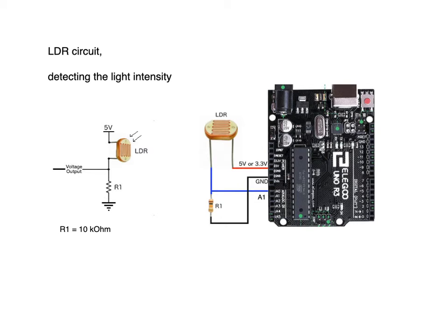We connect the pull-down resistor between the LDR sensor's other pin and the ground. The sensor data is taken from the same pin where the resistor connects, and it's connected to the Arduino's analog pin. Any of the analog pins from A0 to A5 should work, but make sure that the pin that you select is the same pin that you code in the Arduino IDE sketch.